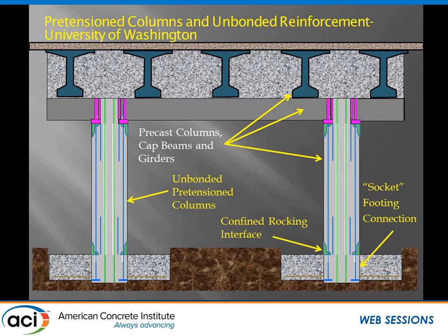So they're pre-tensioned, but they're pre-tensioned and unbonded, so a little bit different combination. You can see that at the ends of these columns, they are pre-tensioned. But in this portion of the member where there's kind of that white around the green, these are unbonded. So the tendons are bonded here and then unbonded along their length.